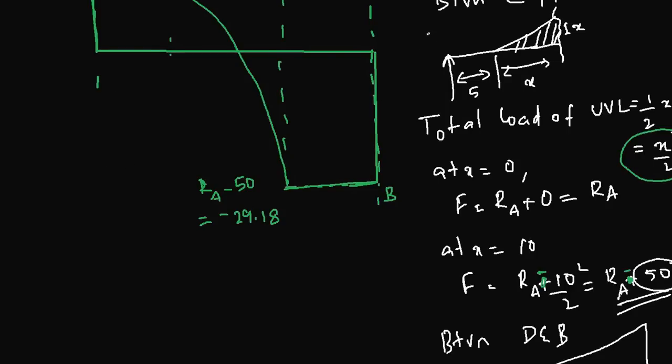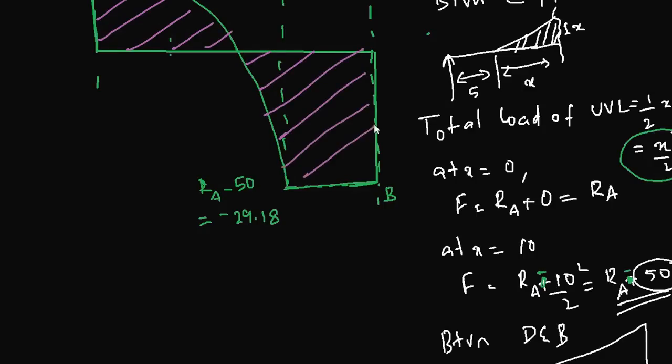So that gives you the complete shear force diagram. Now just make sure this is a curve. This is a smooth curve. I can't draw this here because of the limitations of this software, but just make sure this is a smooth curve. It's just a curve like this, and a smooth curve. It's just because that variation is based on a square law that you have a curve there.